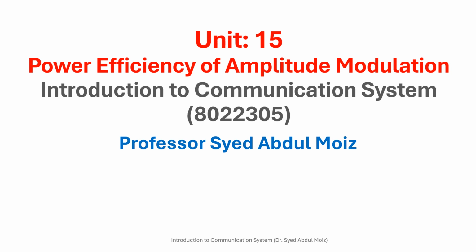The power efficiency of amplitude modulation refers to the proportion of the total transmitted power that is effectively utilized in conveying the actual information signal or message, compared to the total transmitted power including the carrier. In standard AM, most of the transmitted power is concentrated in the carrier, which does not carry any information, and a smaller fraction is allocated to the sideband where the information resides.